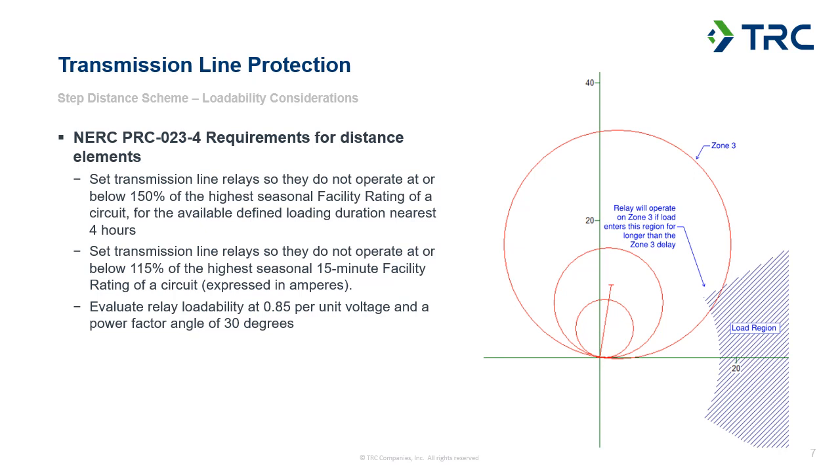And there's different ratings for how long system operators can operate their transmission lines within those ratings. So typically you may have a 4-hour long-term emergency rating and a 15-minute short-term emergency rating, and maybe even a couple other ratings past that, based on thermal modeling of the transmission lines and the expected seasonal ambient temperatures and things like that.